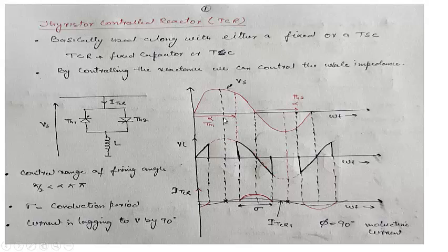and it lags the source voltage by 90 degrees, and it has to be there because this inductor is of inductive nature. It draws the current which lags its voltage by 90 degrees. So this is also as per the general rule. So here phi will be equal to 90 degrees. Actually, we should have phi 1, that is the power factor angle, or we can say phase angle of current, but it should be the fundamental component of the current. It is inductive current. So we can say that current is lagging the voltage by 90 degrees.